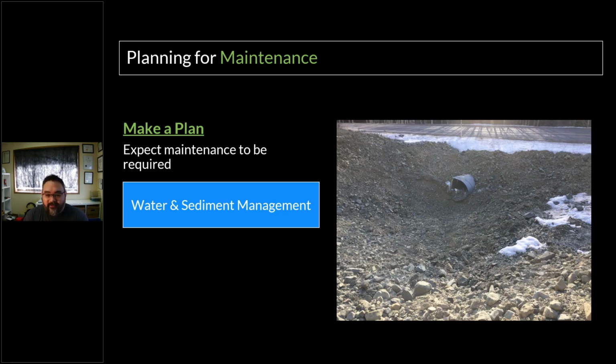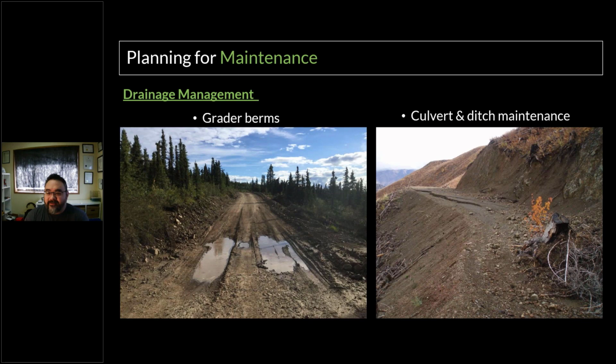And what are the main things? They're water and drainage management, and then that surface management. And so the most common thing is grading. Kind of an extreme example on the left-hand side, but what are the critical elements? Well, they're crown and surface water management. So that ensures, and it's not just about the environment, it ensures that we have faster traffic volumes. Our surfacing is more resilient because we're shedding the water off it, and we're not having potholes, which cause vehicle damage,